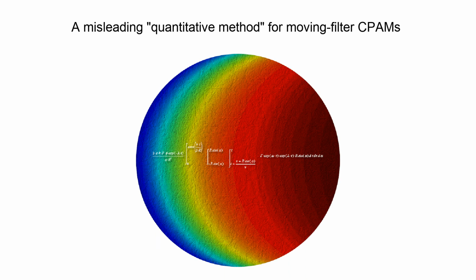A number of approaches to this inverse problem are addressed in detail in the referenced paper. Each method has its advantages and disadvantages, as one might expect, and a method that might work well for a fixed filter monitor may be useless for a moving filter monitor, or vice versa. One important conclusion from this paper is that for all practical purposes moving filter monitors are not usable for quantitative estimation of a time-dependent concentration.